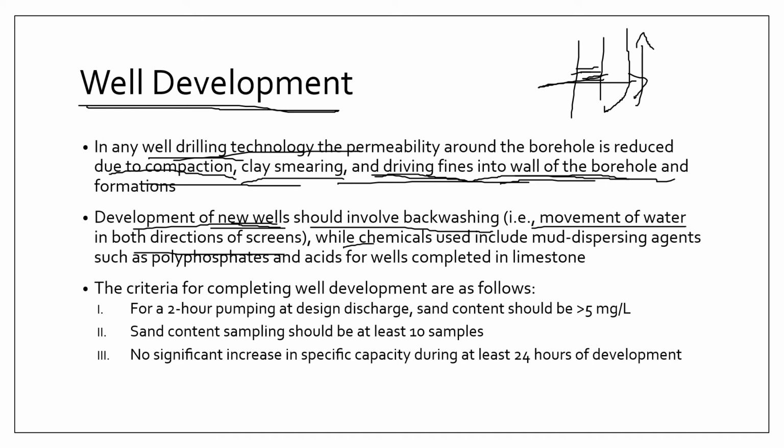Sometimes chemicals are used, and these typically include mud dispersing agents such as polyphosphates. If you're dealing with limestone formations, you might also need acids, which are there to dissolve or widen the fractures around your limestone formation.